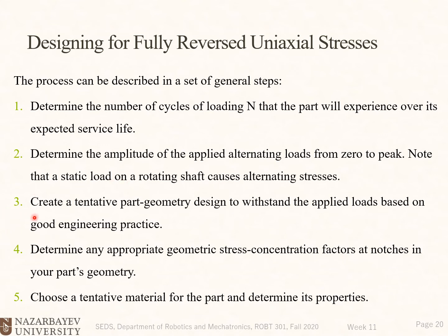Third, create a tentative part geometry design to withstand the applied loads based on good engineering practice. So you need to assume some part geometry based on your design and proceed with that geometry and see if that geometry works. Fourth, determine any appropriate geometric stress concentration factors at notches in your part's geometry.